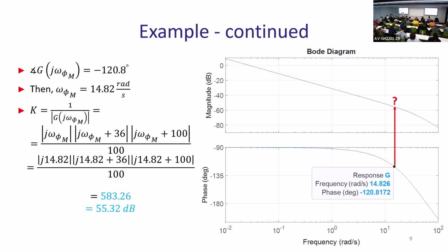So you picked the point where your margin was the desired phase margin. It was not phase margin in open loop, okay? It was just phase which contributed exactly the number of degrees that you wanted. And then you modified the gain to match 0 dB exactly at that crossing point. Where did we pick that crossing point?